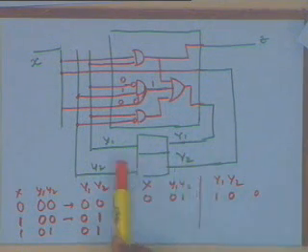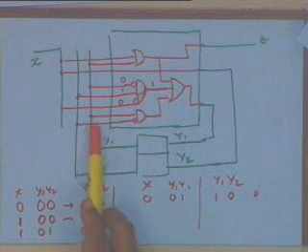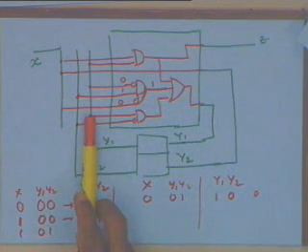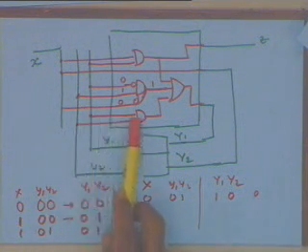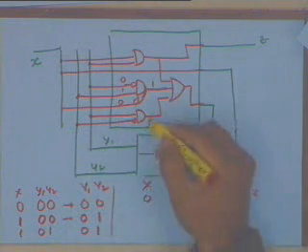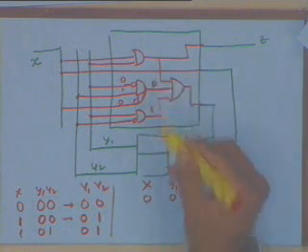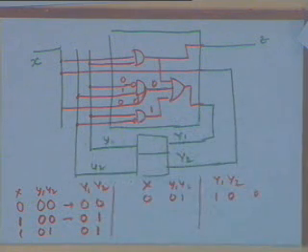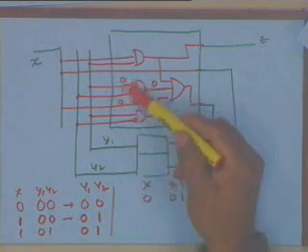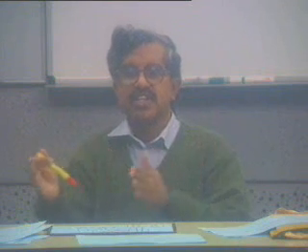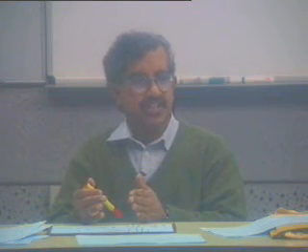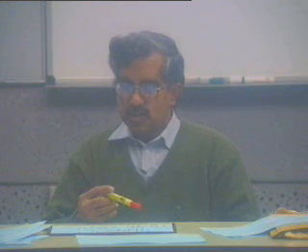But because once this became 1, this one will, if it comes over here, y1 1 and y2 0 will make this one, and this one will hold on. So this will eventually become 0 and this will hold on. But an important point over here is, this is the gate which generates this transition. Please remember, in synchronous sequential circuits, these things were being done by the clock. It was very nicely differentiating between the present state and the next state. Here there is no such clock. So I have a problem.